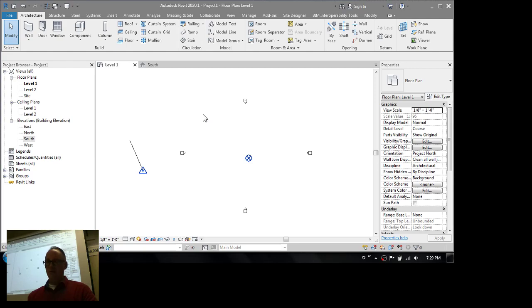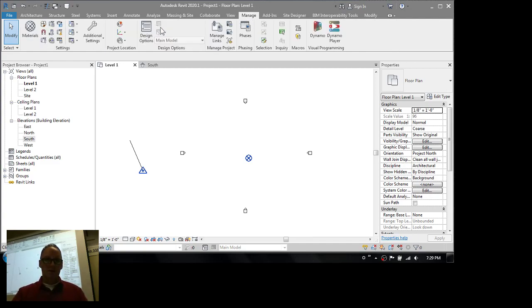we've talked about the first bullet point icon where we can select the project base point and then type in the declination angle ourselves. Now we are looking at the second option. On the Manage tab, I think it's the coordinates drop down or position menu. Anyway, it's this one, the bottom of the 3. I don't have text showing because I've changed my screen resolution to suit the screen. So here we've got rotate true north.